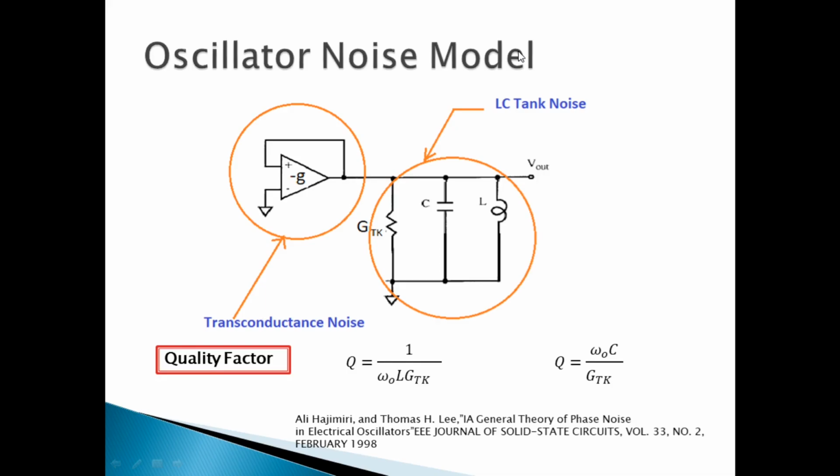So, what we will learn today is about the mechanism behind phase noise generation in oscillators. Of course, we will apply analysis to the prototype circuit. It holds good to any sort of harmonic generators that are present today. We will be dealing with noise generated by the LC tank, also dealing with noise generated by the active part or by the source.